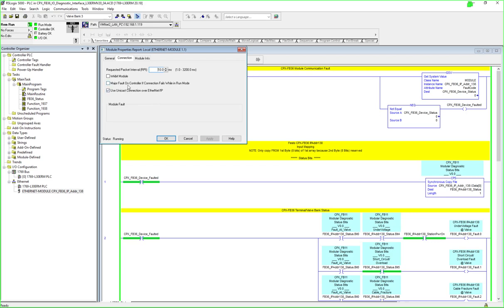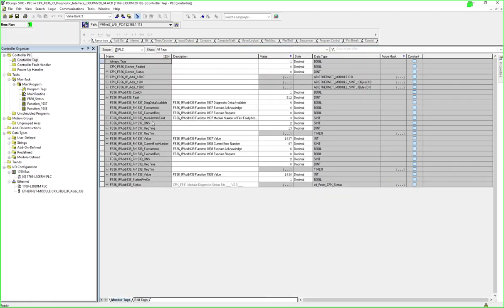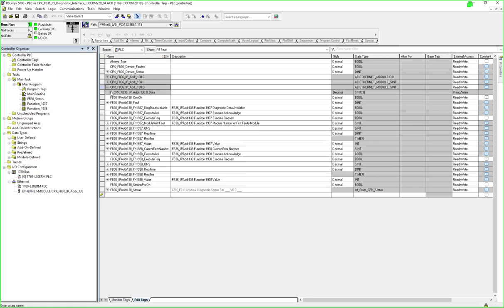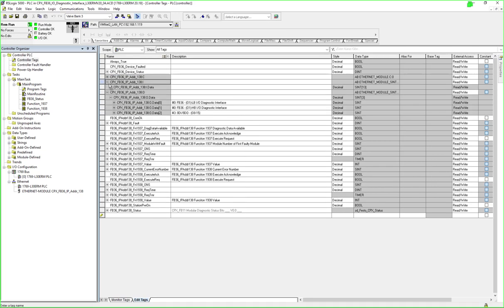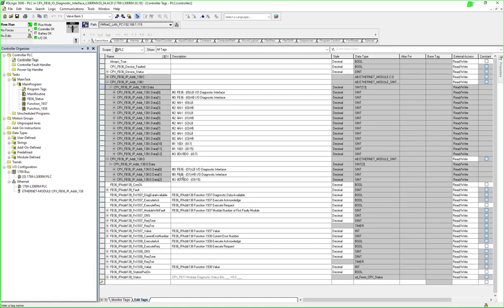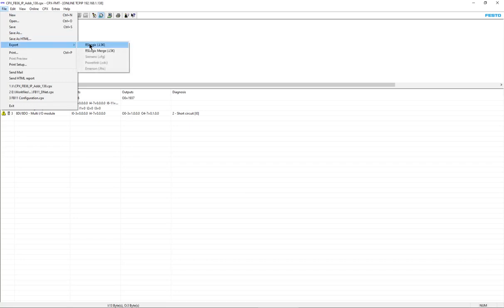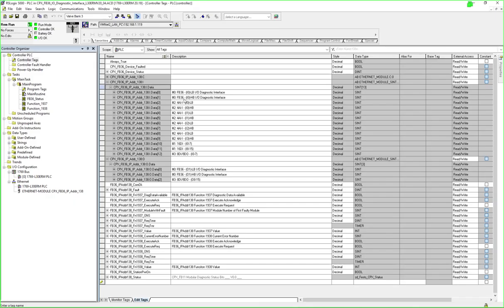When you do an export, typically you have to turn this unicast on if you're in an older Rockwell PLC because it's default off. You don't want to be multicasting messages. So once we have this connection in the controller tags here, we always have the gray tags, and it's created the data here. And the nice thing about doing the export from the Festo maintenance tool right here and then importing into here is that there are some descriptions here.